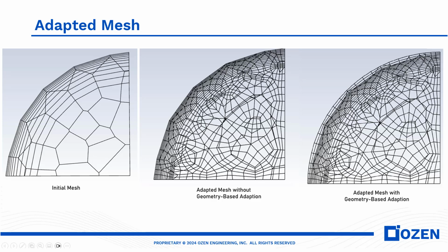If we rely only on the criteria available in Ansys Fluent for mesh adaptation based on the solutions, for example gradient based criteria, this is what we got. We refined also the boundary layer at the wall and the mainstream flow. As you can see, I have many more cells here compared to the initial mesh, but still I don't get the results for the pressure drop that I expected.